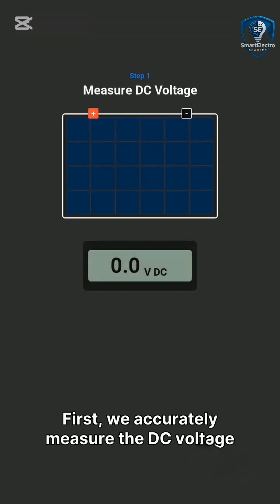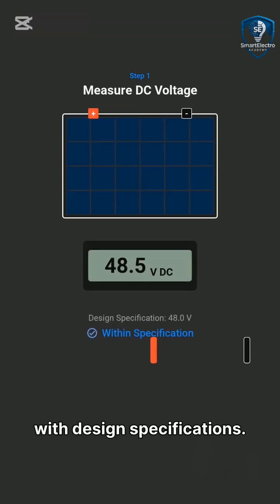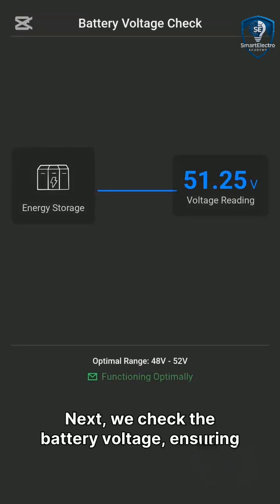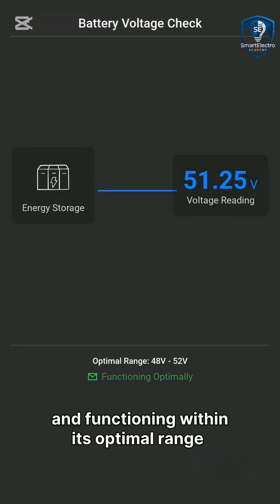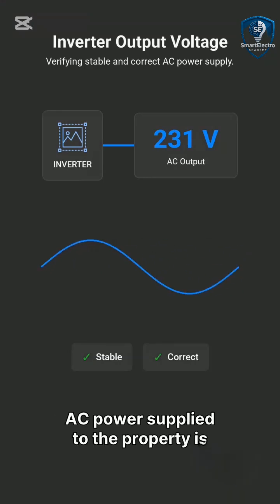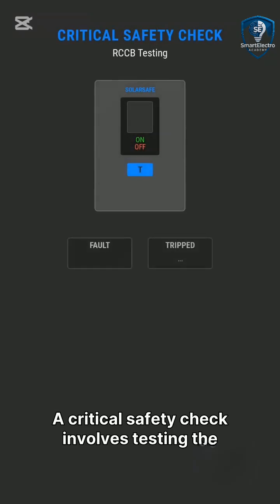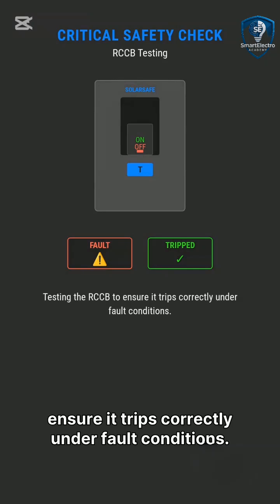First, we accurately measure the DC voltage from the solar panels, confirming it aligns with design specifications. Next, we check the battery voltage, ensuring the energy storage system is correctly charged and functioning within its optimal range. We then verify the inverter output voltage, which is crucial for confirming that the AC power supply to the property is stable and correct. A critical safety check involves testing the residual current circuit breaker, or RCCB, to ensure it trips correctly under fault conditions.